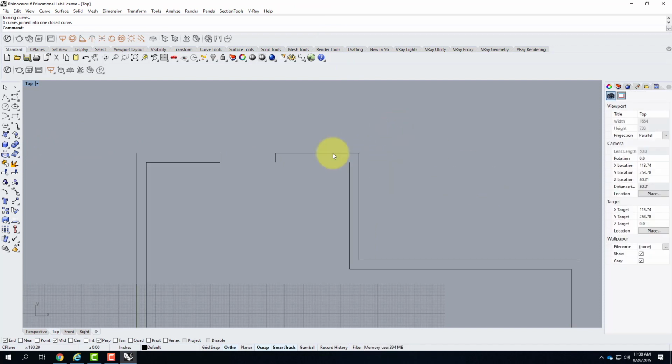It's time to go ahead and draw in that front door. I'll use a rectangle tool. This is my rectangle corner to corner tool. I'll snap right to that corner there. And here's a perfect opportunity to use those coordinates that I was talking about earlier. So this would be at negative the thickness of the door, so 1.375 for 1 3/8, comma, negative 3 feet for the length of the door.